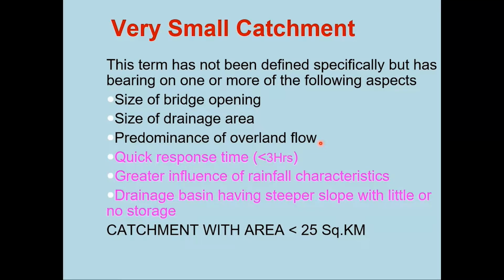Though when we use the synthetic unit hydrograph, we add both things: the inland flow, meaning the water which comes as seepage into the stream, is added, and the water which will get absorbed by the earth is deducted during the synthetic unit hydrograph method analysis. But in this analysis, these two items have not been accounted for.